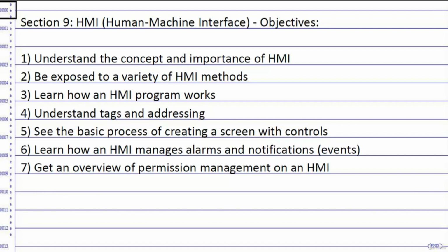Other than that, setting up alarms in a PLC is the same as almost any control. You associate each alarm with a tag. You generally put a message in, and you're going to want to have two different controls for most HMIs to manage alarms. You're going to want to have, at a minimum, an alarm reset and an alarm silence button, and those are going to tie back to the actual management of the alarms and notification bits inside of the PLC.